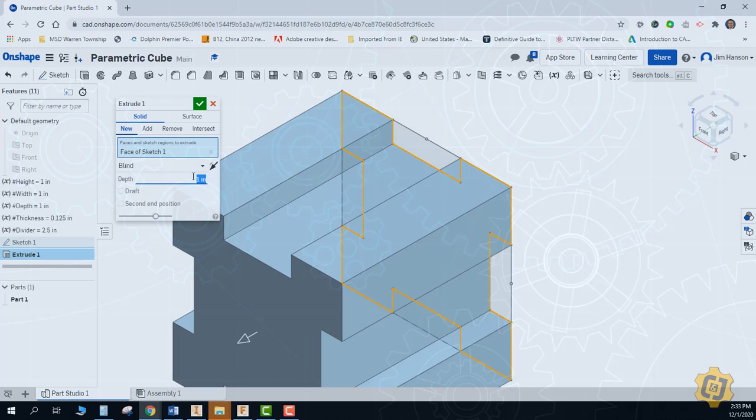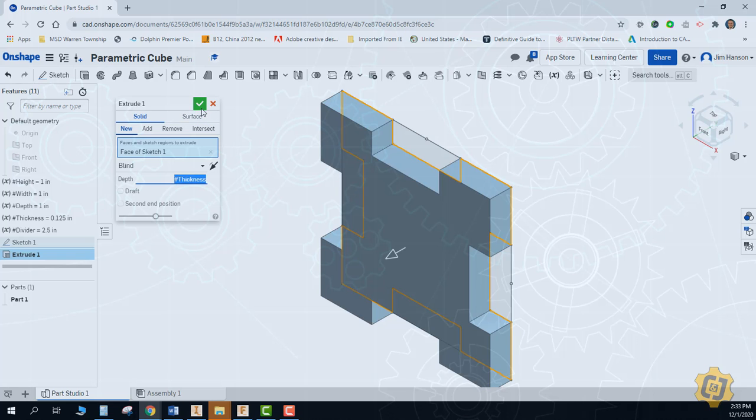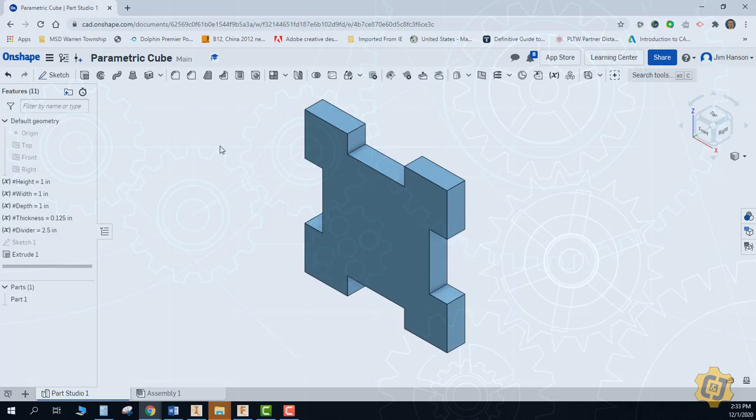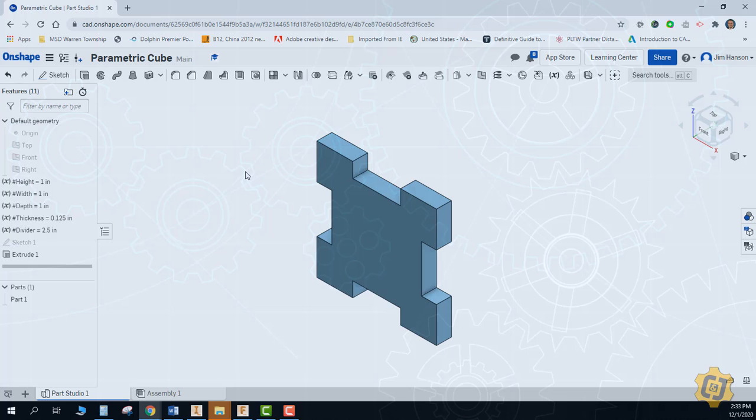And then I've already defined this as thickness. I've even already used it in my formulas. So great, I have one piece completely done. And remember, in here, all I need to do is design the 3 pieces as components in place, and then I'll go ahead and drag them over to the assembly. Okay, so now I need to decide, am I going to do the one that has all tabs or the one that's 50-50? Let's go ahead and do the one that has all tabs.